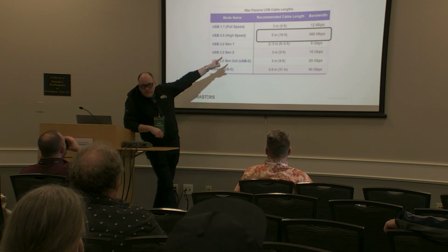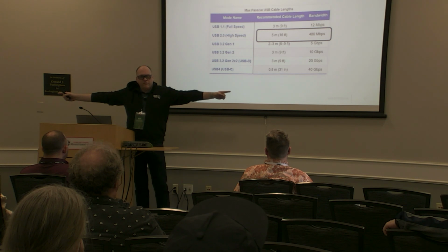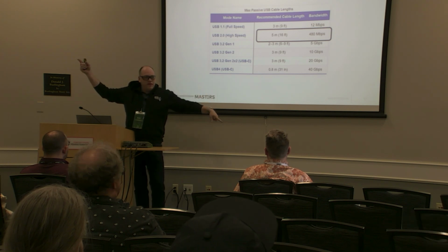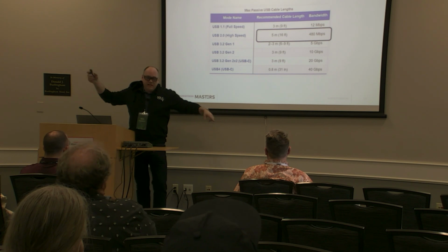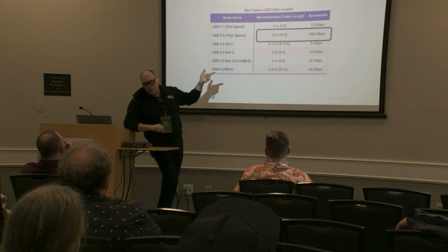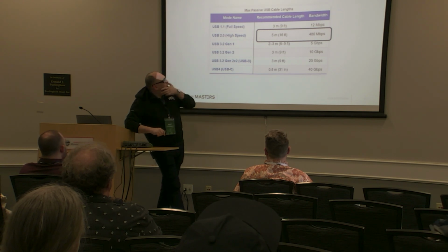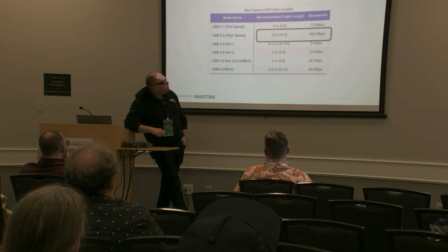5 meters or 16 feet, that's the max limit of a cable, right? So if you've got a 25-foot USB cable that you're trying to get across a table from a camera or a keyboard to a PC, it's not going to work, right? Because that's our max limit based on Ohm's law, essentially. That's what's happening here. We can't get the power to power it up. And the data won't propagate through the capacitance of the cable.